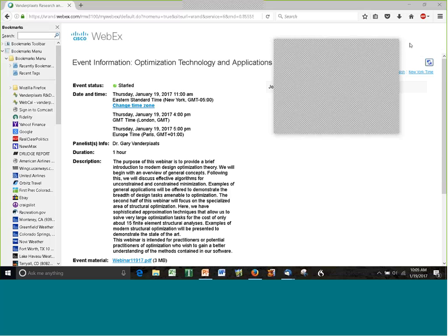I think we can have thermal loads, right? In Genesis. Actually, yes, you can have thermal loads, and like you, I'm not sure why it is not used as much, but I would like to add that starting with Genesis 16, which is the next version, we should be able to design topology with a heat transfer load case. So you can use temperature as an objective that's coming from the heat transfer and minimize that temperature.